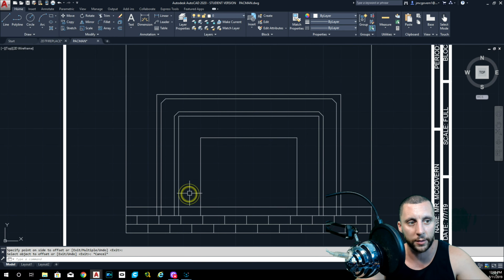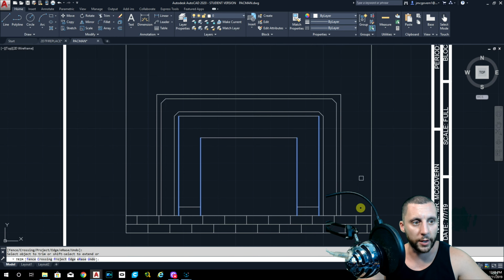So if I go 1 like this, I don't want to keep doing that. It's going to be a ton of trimming. Let's get the first trim done. Let's do an old school trim. Let's click these two and these two. We'll do it all in one shot. And if you click something outside of that area, it'll trim the rest of that area off. So now we have just those two lines.